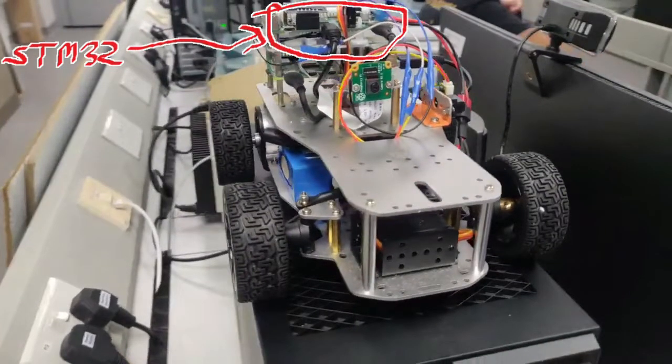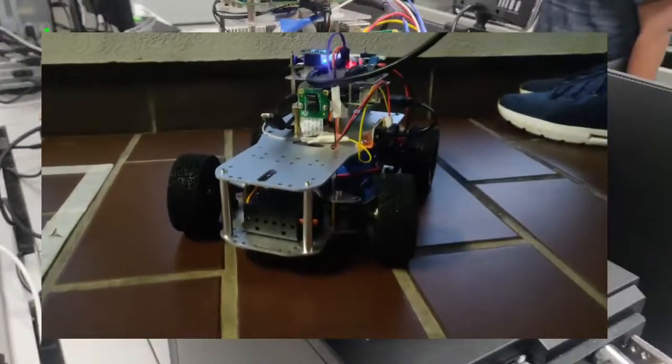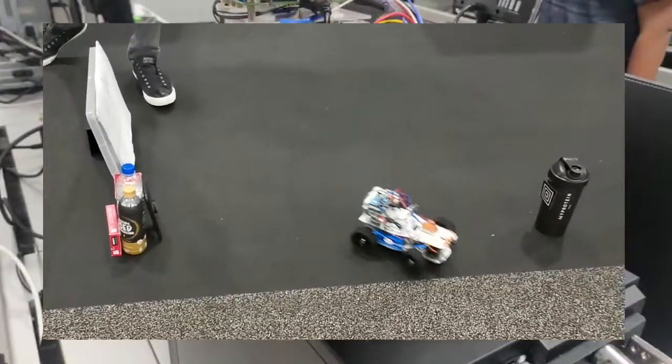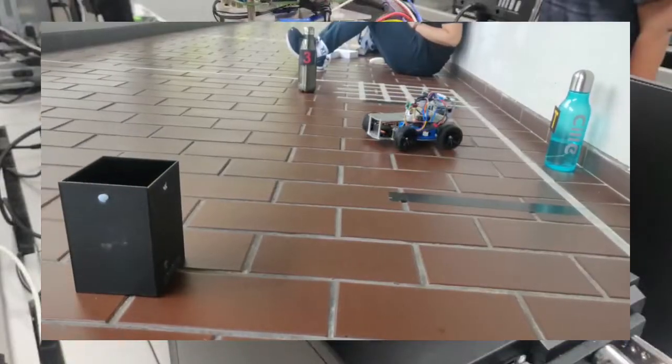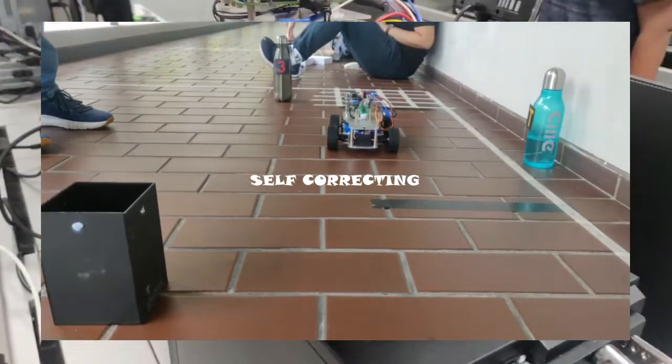This is the STM32. We used it to control the actual movements of the robot using two motors in the back and a servo motor in the front. Now we found that the robot would move slightly differently over different runs using the same settings because of slight differences in each wheel and the differences in the flooring that we were running on. So to correct for this, we had to implement a self-correction mechanism.